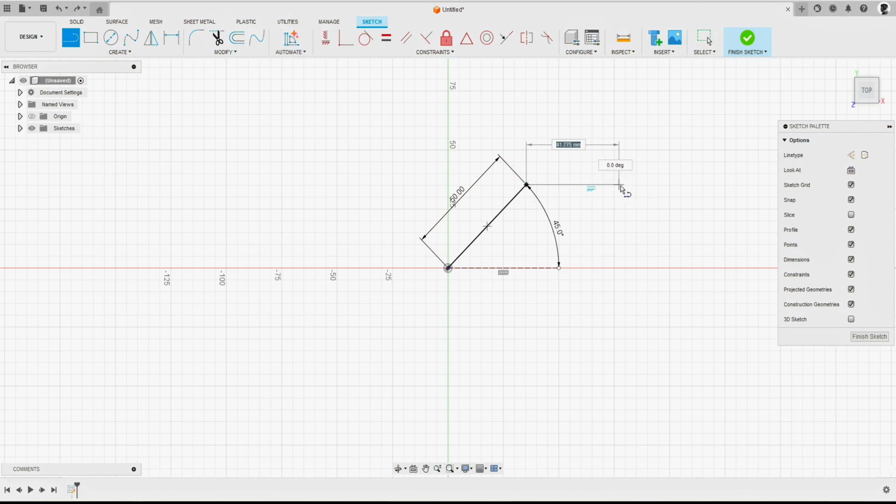If you want to turn off grid snaps, come down to the grid and snaps, then you can turn off snap to grid. But for me, I'm going to keep that on throughout this course. I'm going to come across, and I'm just going to drop the line. Let's just say somewhere here. Bring this line down again, left click once, come across here, left click.